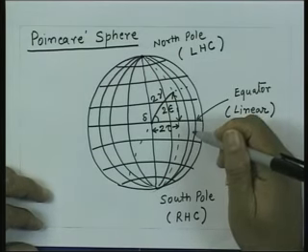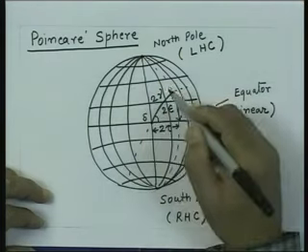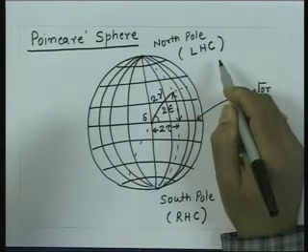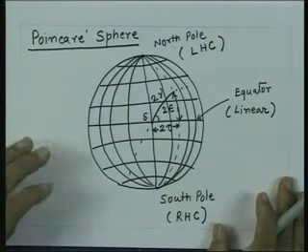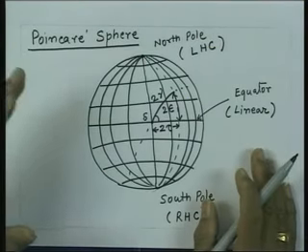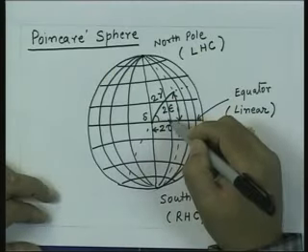What that means is that points which lie in the northern hemisphere essentially represent left-handed rotation, because we saw from our earlier discussion that if Ey leads Ex, then the sense of rotation is left handed. If Ey lags Ex, then the sense of rotation is right handed. So, in this case, since delta is positive or epsilon is positive, we have a sense of rotation which is left handed,